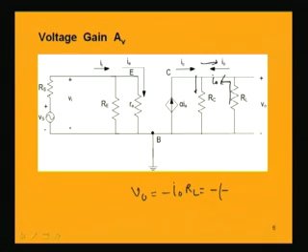So, this I naught is basically minus IC into RC by RC plus RL, multiplied by RL. So, ultimately it will be positive. So, it is IC into RC parallel RL that is the V naught.